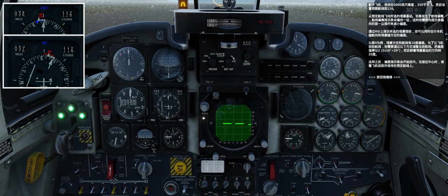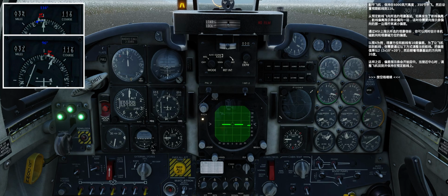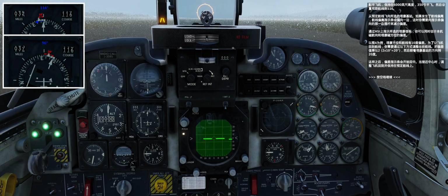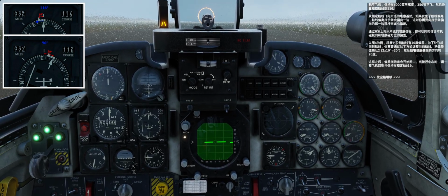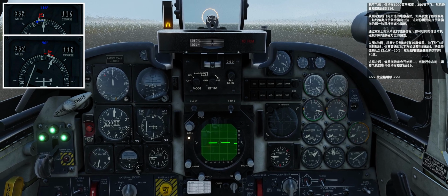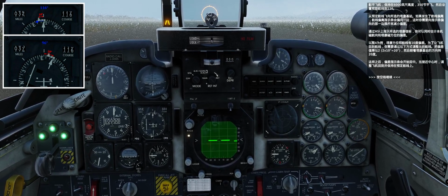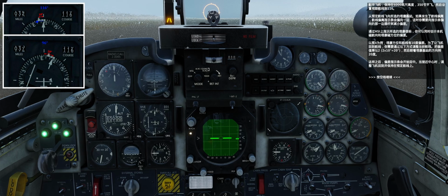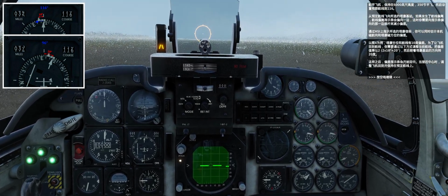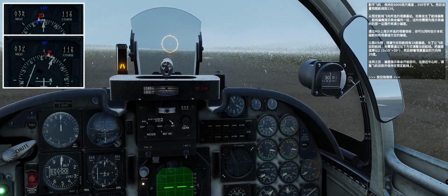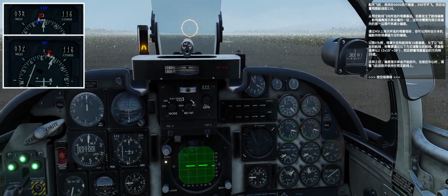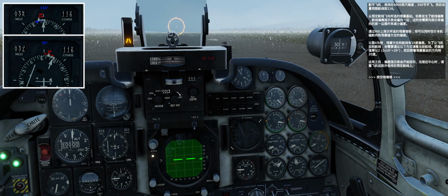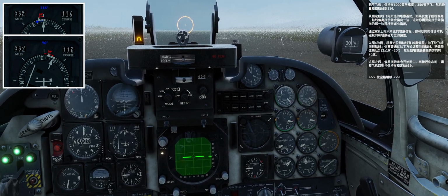In case of course deviation, the deviation bar will deflect to the side, to which you must turn to compensate for the deviation. Using the triangle on the HSI, which points to the selected TACAN beacon, you can also estimate relative radio bearings by the difference between your current course and beacon bearing. The example, shown on Figure 4, shows a situation where the TACAN bearing differs from a course of 10 degrees. To return the aircraft back on course, you must adjust the current course using the following approach.